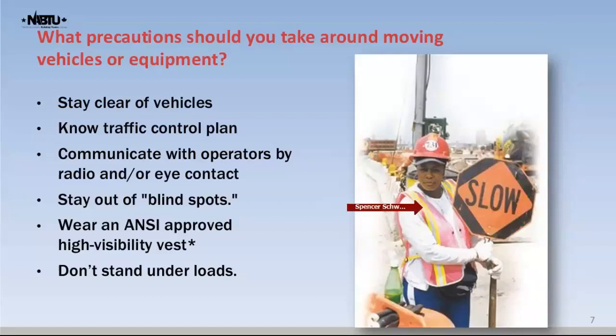And you don't want to stand under a load. So if you're unloading equipment, if you're working around cranes, I'm going to repeat that a number of times during this presentation. Don't stand under a load. Don't walk under a load. If something is suspended, there's all kinds of things that can go wrong with that operation, and you just don't want to be underneath a load where stuff could fall and hit you.